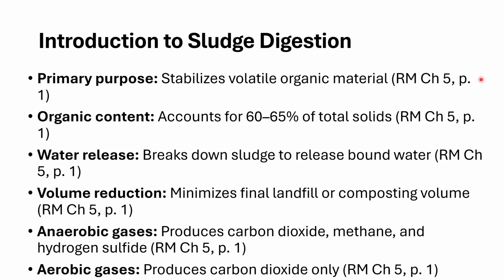So sludge digestion. We talked a little bit about this. We went over solids handling last lecture, so let's catch ourselves up. We started with preliminary or pre-treatment, if you will, and that was basically removing the large debris from our incoming influent, our wastewater stream coming from the collection system and then coming into the plant. And we got rid of wipes, rags, branches, debris, any of that stuff. We're looking to get rid of bigger stuff that could harm our equipment or interfere with our process.